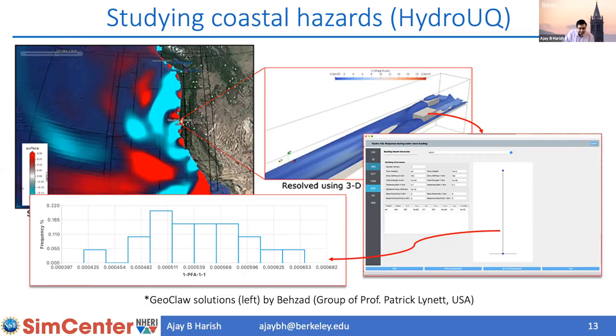So this picture depicts what the HydroUQ tool does. People ask me, on the right side, what is it? Is it a flume? So that's where the image is bringing a double message. One thing, we can do multi-scale modeling. And second, we have digital flumes that you can use for experimental setup in a way. So it's conveying two of these images. And you can build structural models and get an uncertain, let's say probabilistic, response. It's not like, okay, my deformation is 0.01, but it's 0.01 plus or minus something. So there's a variance, and this is my stress and there's a variance of this. That's what we can get out of the HydroUQ tool.